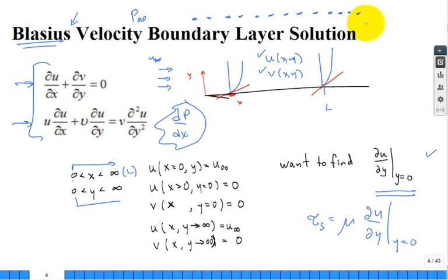There's no reason that the pressure changes far above the plate, even in the direction of flow. Now, what you're thinking of is pipe flow, internal flow, and the pressure in the middle of the pipe, and the pressure is going to drop as you go down the pipe. But this is external flow, and far above the plate, the pressure is not changing in the x direction or